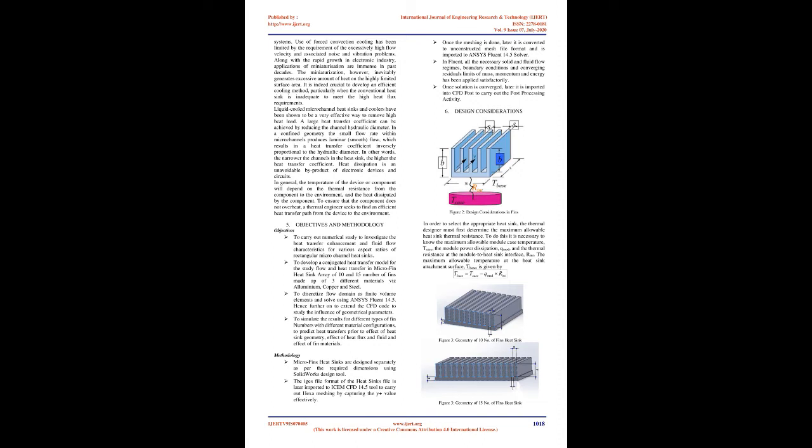Xie et al. [13] had studied recently the obstruction induced in the path of the microchannel heatsink. They reported that the boundary layers get destroyed and new boundary layers are built, which aid in the thermal performance of the heatsinks. They evaluated that obstruction length plays a dominant role in thermal performance of the MCHS. Latest researches are investigating the effect of magnetic influence, porous medium, and nanoparticles in enhancing the heat transfer characteristics of liquid coolants used for various applications including MCHS and have been briefly discussed as follows.